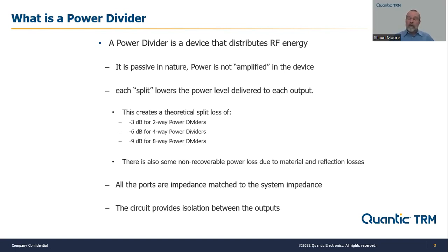And for most of the designs that we have for this sort of device, there is isolation between the output ports, which means that any signal that gets reflected back won't be shared among all the other devices that the signal is being distributed across. That isolation helps with a lot of system performance requirements.